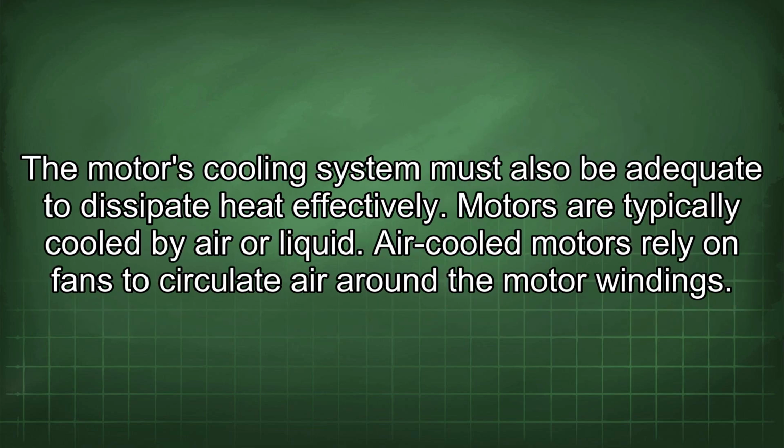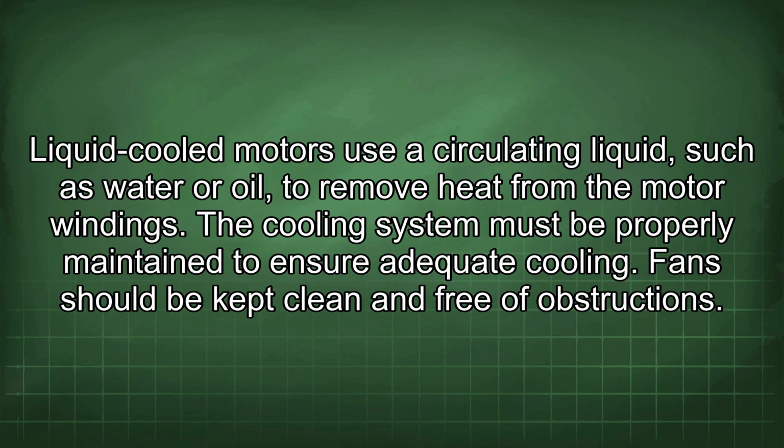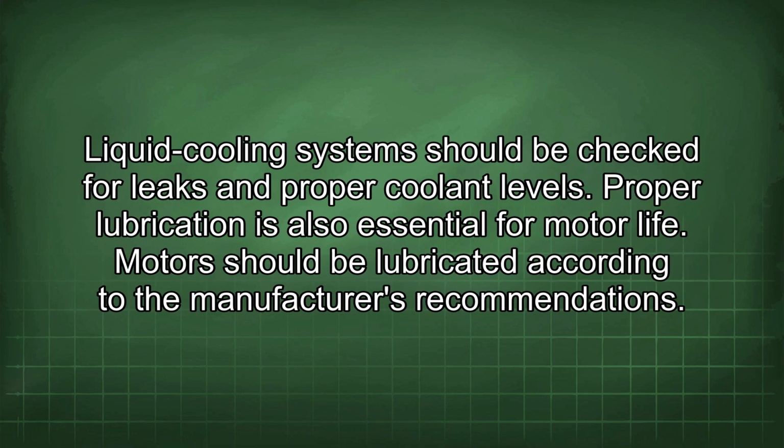The motor's cooling system must also be adequate to dissipate heat effectively. Motors are typically cooled by air or liquid. Air-cooled motors rely on fans to circulate air around the motor windings. Liquid-cooled motors use a circulating liquid, such as water or oil, to remove heat from the motor windings. The cooling system must be properly maintained to ensure adequate cooling. Fans should be kept clean and free of obstructions. Liquid cooling systems should be checked for leaks and proper coolant levels.